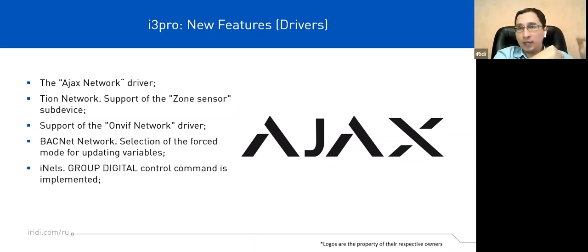And after that, this controller will send us any updates for these variables. And the second way looks like Modbus. I mean, we always ask this controller, what changed, what news, what about this variable, etc. And of course, the more interesting part is the first way.